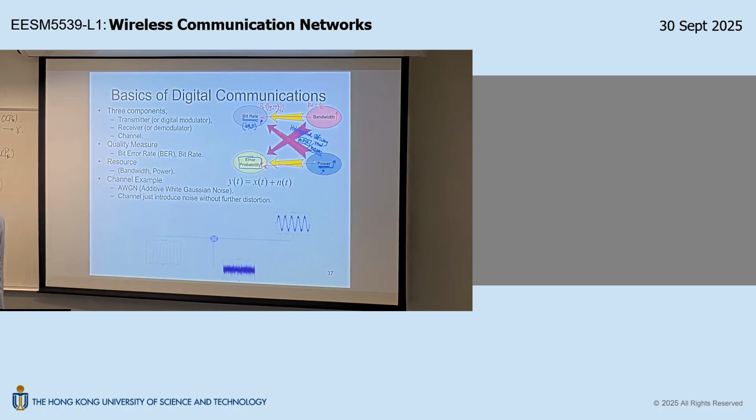And typically, if you go through a field test measurement in a cellular network, the typical SINR is just around 30 dB on average. So 30 dB is far from sufficient to support 4096 QAM, okay? That's why in cellular networks, they never design this into the transmitted modulation, because even if they put in 4096, you never get a chance to use it, okay?